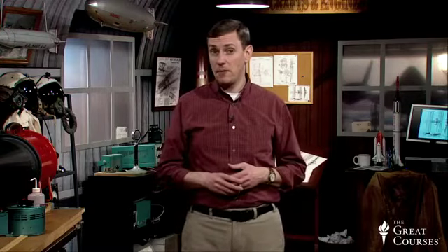The transition between laminar and turbulent flow is notoriously difficult to get right in a wind tunnel. Reynolds number, which indicates the relative significance of viscous effects, is a helpful parameter here. Aerodynamicists attempt to match the Reynolds number in a wind tunnel environment to what is encountered in flight, but problems such as the turbulence intensity level of wind tunnels are still difficult to overcome.